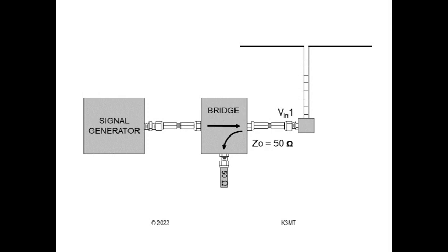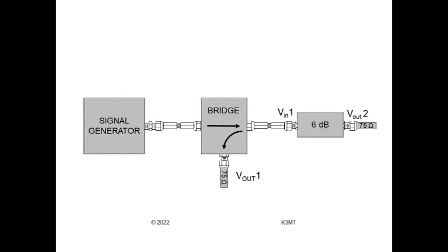Here's another example, an attenuator. It's a two-port network. S11 is the power reflected back to the signal generator. And S21, the reduction of power coming out the other side, is the attenuation, usually expressed in decibels. A proper attenuator will have S11 equal to 0.